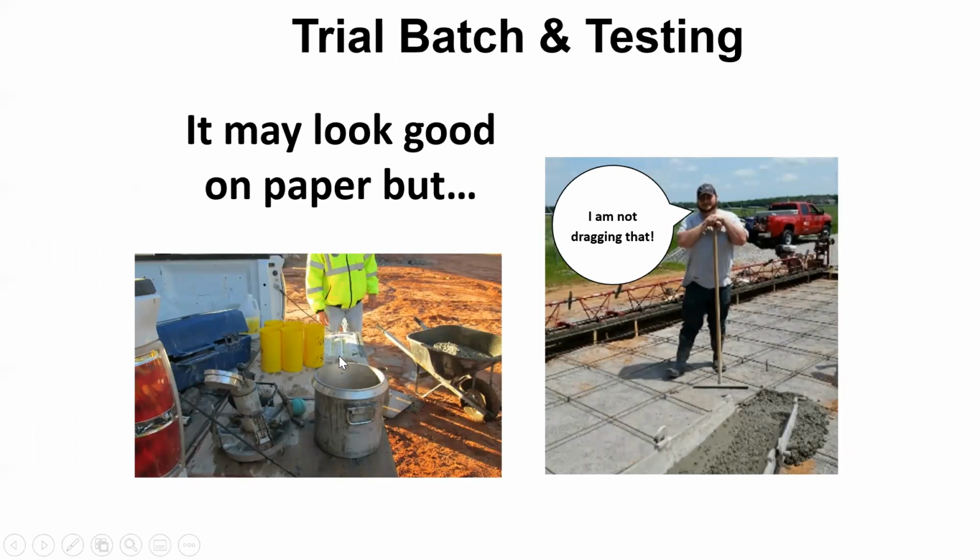And like I always say, trial batching may look great on paper, but you have to go out in the lab, go out in the field, and actually figure out with that new mix how it looks. So I always tell people, when you design in general, how you get real experience is you go out and look at your designs.